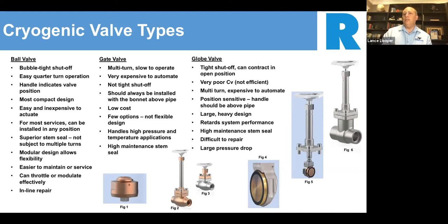We also have a full range of gate valves as well. I don't know if you guys are familiar with gate valves or see a lot of these in the industry. They're mainly focused on the trailer side of our business. You see a lot of gate valves on trailers, and this is usually because of full flow. If you look at figure 6, 5, and 4, that's our standard Hiroshi brand of gate valves that we offer. It incorporates a wedge that you see in figure 4. It basically is a linear movement, going up and down within the valve body.